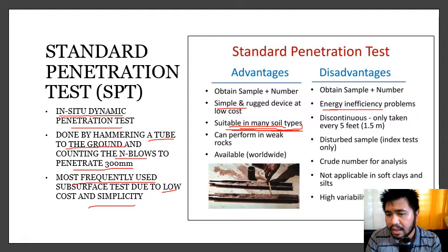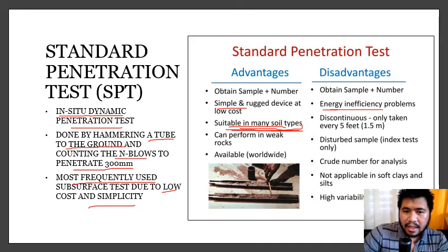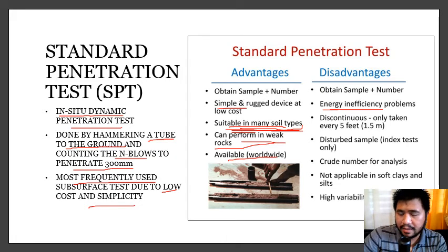In geotechnical terms, they may not contribute to the strength of the soil, but once the SPT encounters that, you can get artificially inflated numbers. You can get artificially high SPT readings. Can it perform in weak rocks? Yes, that's possible, but it's not really recommended. Available worldwide.